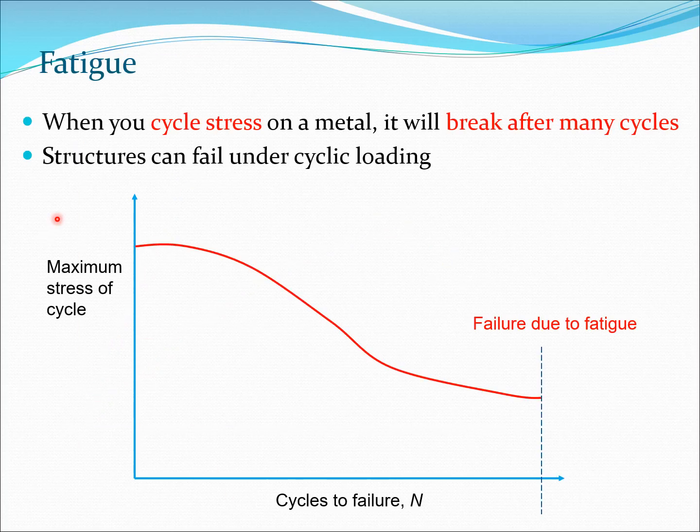Now, besides this kind of strength-based thinking, we also have a problem known as fatigue, which takes place in materials. So if you take a certain metal or any material and you impose cyclic stress on it, then what will happen is that if you keep subjecting it to these cycles, it will break after many cycles. Especially many materials such as those subject to cycles because of rotating machinery, or it may be that an airplane is just taking off, landing all the time and going through these kinds of things which are very large in number over a period of a few years, then it is essentially being subject to this kind of cyclic loading.